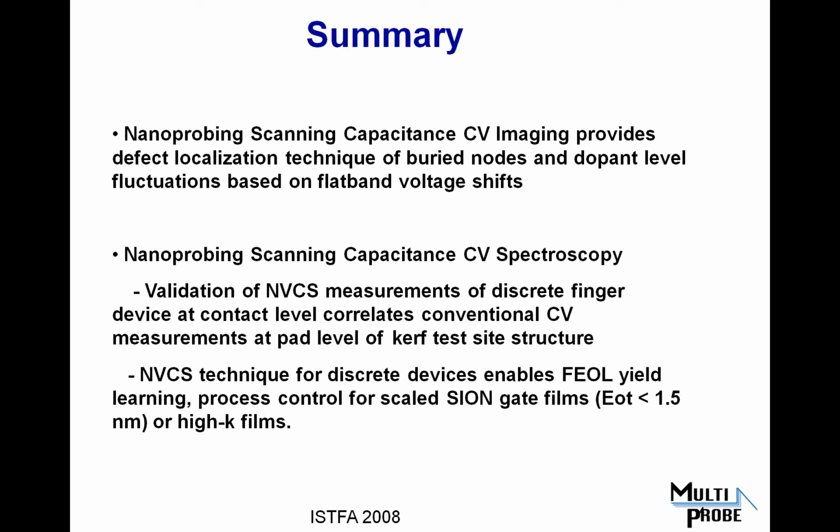So, you mentioned we've demonstrated the ability to match the measurements that are typically done at pad level CV measurements with those with resonant sensor at a discrete device level. And as Andy mentioned, the subtlety of the devices or the defects in devices, as we were talking about sub-45 nanometer type technologies, we have to be more conscious of dopant type fluctuations.